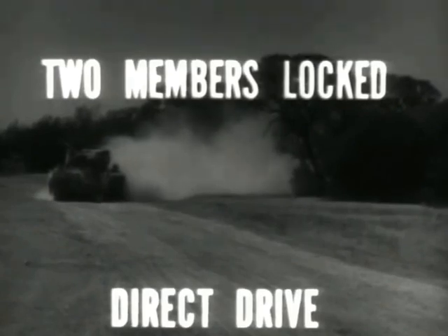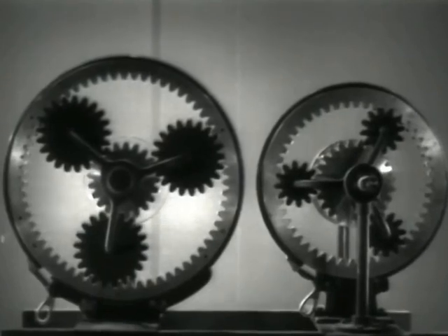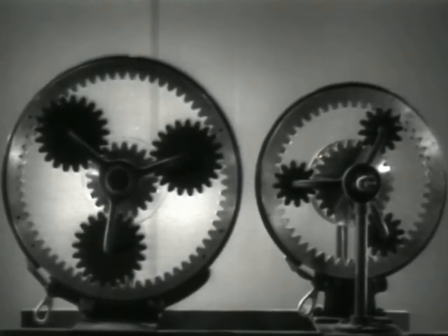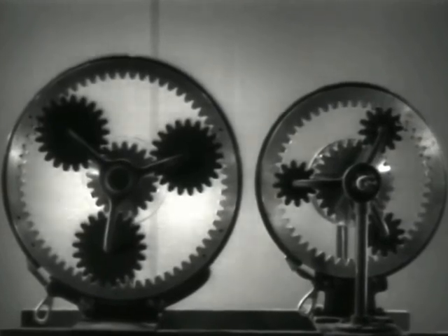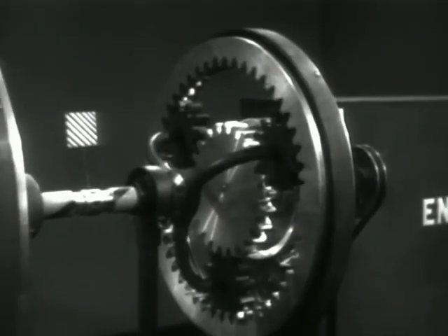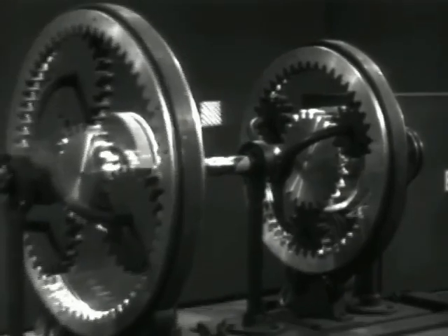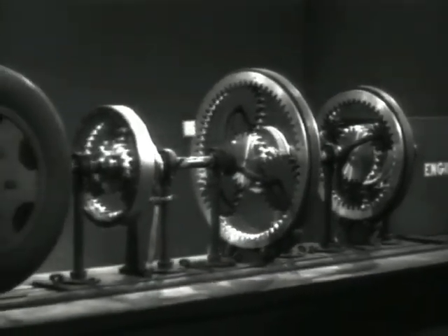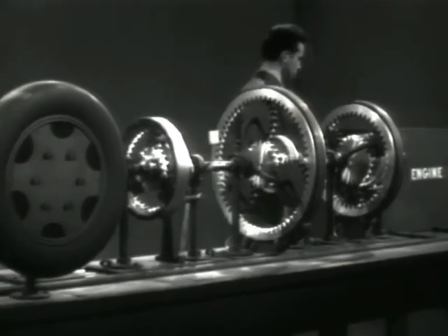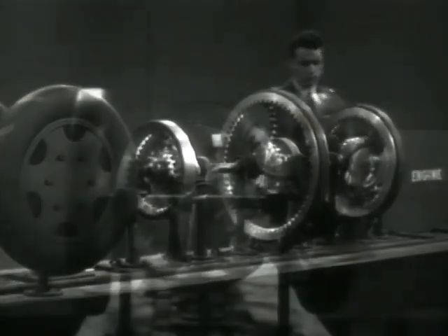But for the mobility required today, many vehicles must have more speeds and capabilities at their disposal. One way to get this required mobility is by changing the relative sizes of gear members in a set. To widen the selection of ratios still more, we can use 2 or more sets in combination. Such combinations, called multiple planetary gear sets, are typical of certain transmissions.